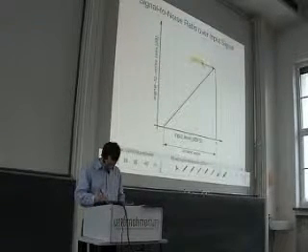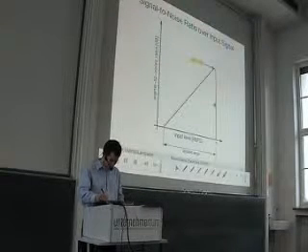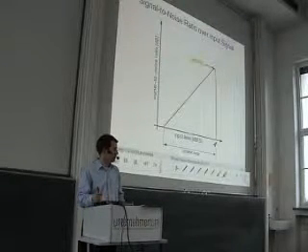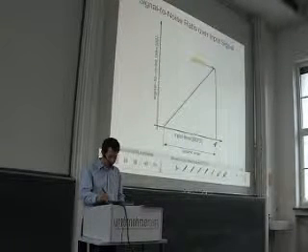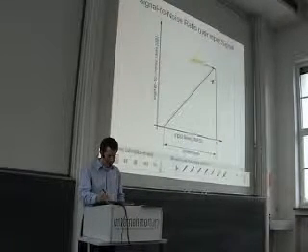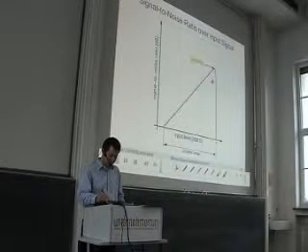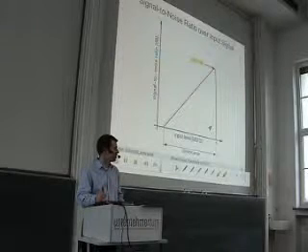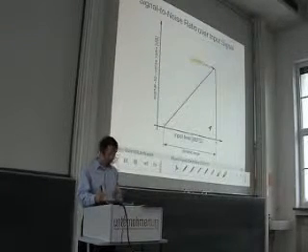And after this peak SNR, we usually fall down rapidly. Beyond this peak SNR, this device cannot work as an ADC. Here we have simply overloaded the device, so the input is too large.